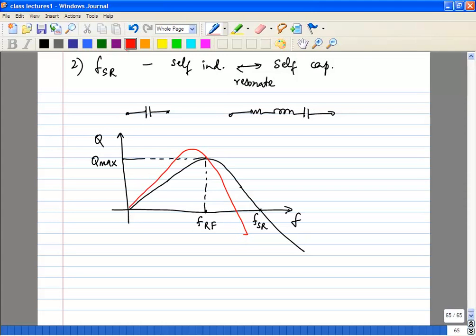So you can choose any kind of inductor topology you want, right? There are different kinds of inductors. We covered one or two in class. If you want to do some extra research and read some paper and come up with a newer structure which gives you better Q, perfectly fine with me. But I'm going to give you a given area, and you need to maximize Q at a particular frequency. So you'll be choosing different architectures, varying the trace width, varying the spacing and so on, in the software. And that will help you understand the trade-offs in inductor design.